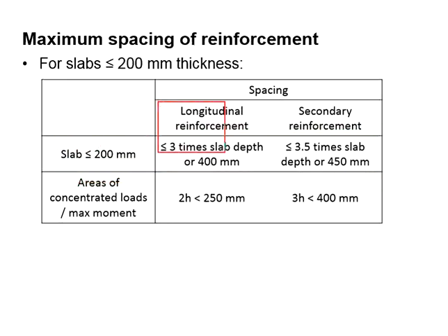You have the main reinforcement and secondary reinforcement. The main reinforcement applies to the shorter span, which is the more critical direction, whereas the secondary reinforcement shall apply to the longer span, the direction which is not as critical.